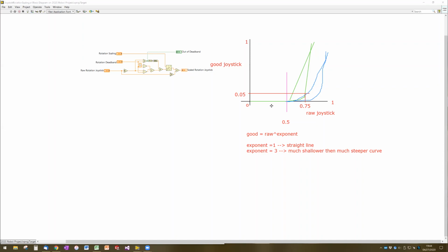In fact, if you could perfectly hold the joystick so the x and y positions were always at the same angle, and you just increase the power diagonally away from the center of the joystick, the angle that the robot would translate in would actually change as the different axes get scaled differently. You'd get different angle goals. Does that make sense, Alex?